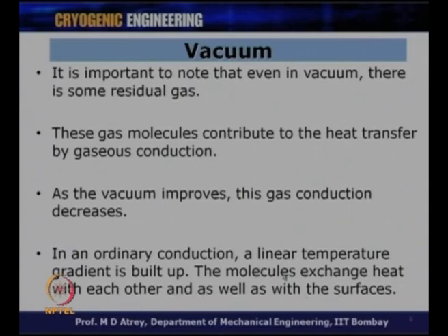So, these molecules are basically responsible to conduct heat from surface at T1 to the surface at T2. Each molecule will conduct the heat to another molecule, and in this way conduction would happen depending on the gas conductivity, and ultimately these molecules will actually touch the walls, touch the surfaces, and therefore the heat will be transferred from surface number 1 to surface number 2.